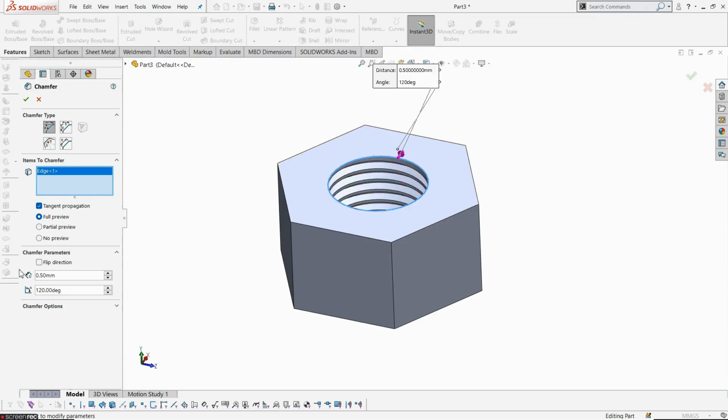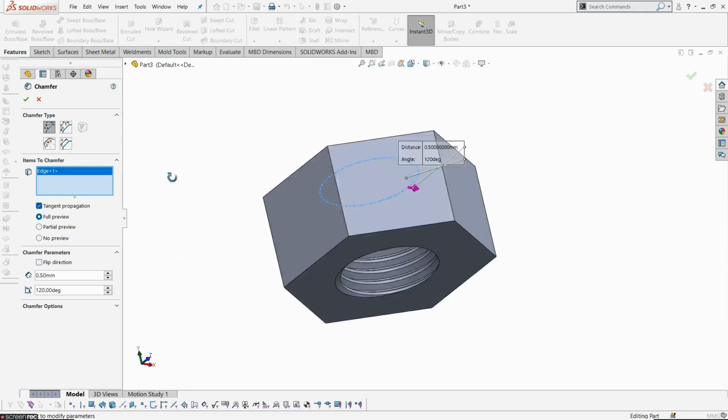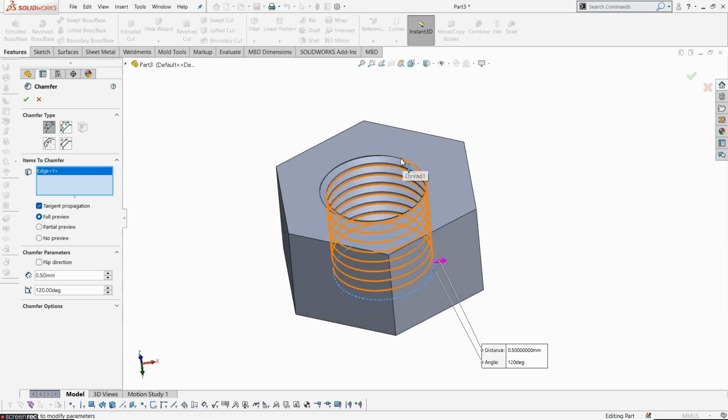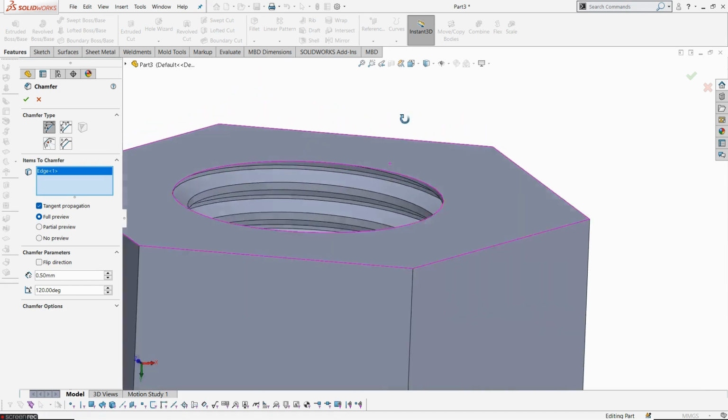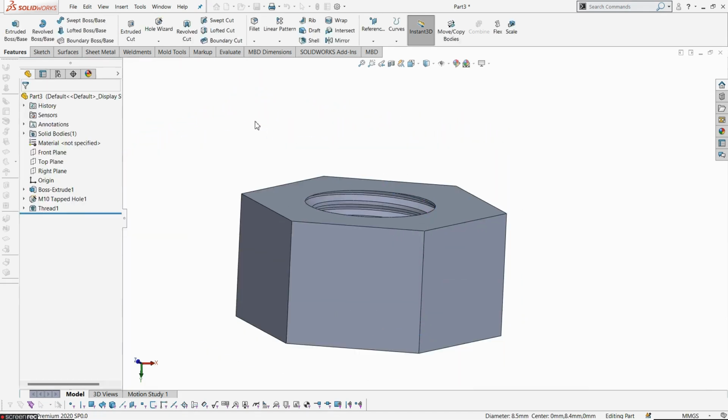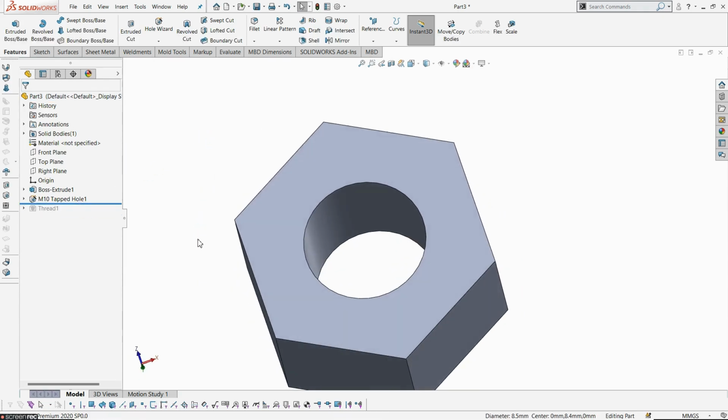Look at it, the chamfer formations are not done in either direction, direction 1 or direction 2. In any case, both the circular edges are not complete within each other because it is completely under the formation of thread. Let's get into the rollback method and apply a chamfer before that.